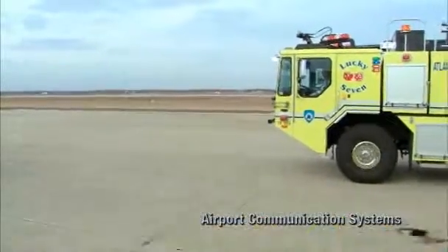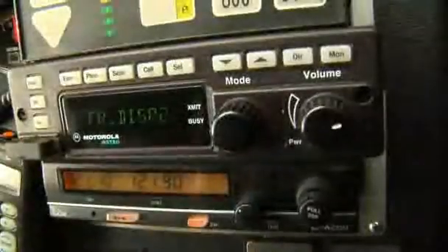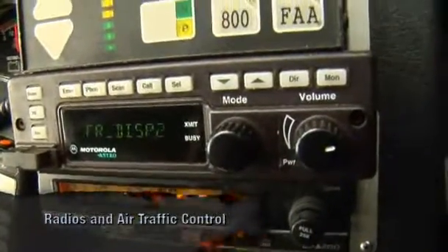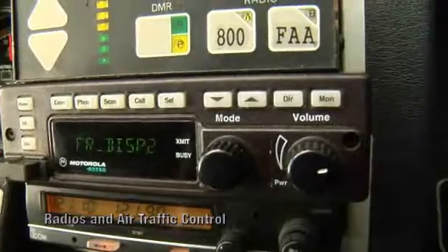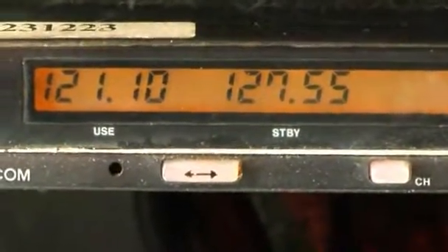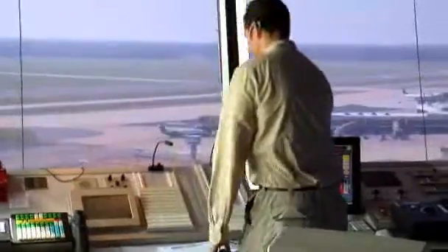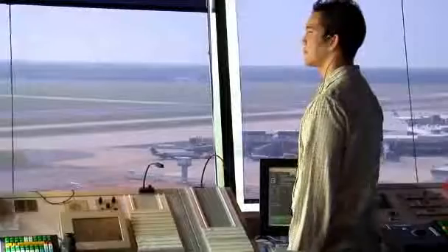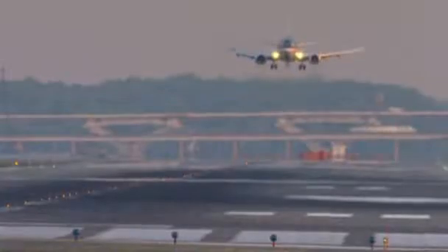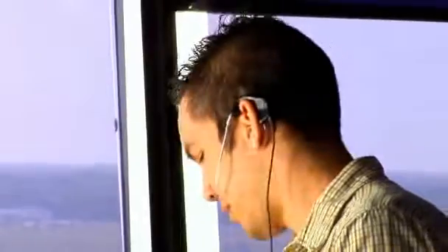The primary means of communication on an airport is aircraft or aeronautical radio. ARFF vehicles should have appropriate radios on board. They should be capable of transmitting 5 miles on any 25 kHz channel between 118.0 and 136.975 MHz. Air traffic control and air carrier aircraft typically use the VHF band. Aircraft approaching, landing, or taking off will use the runway or tower frequencies.